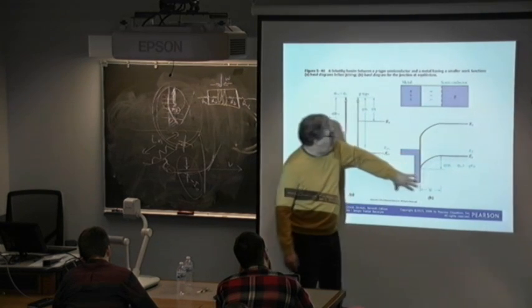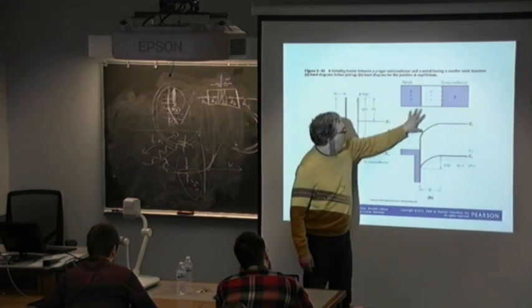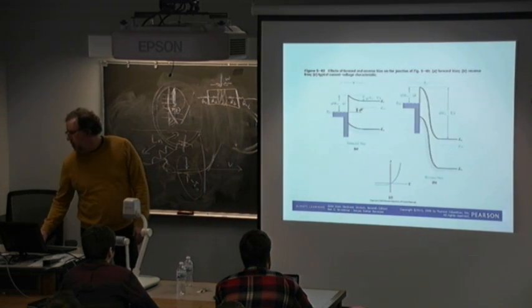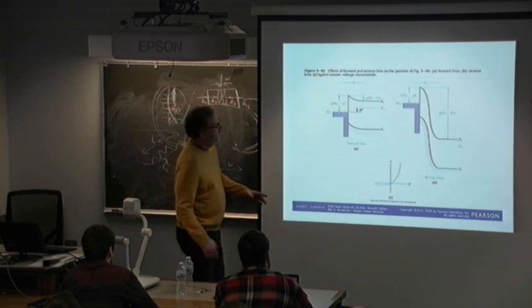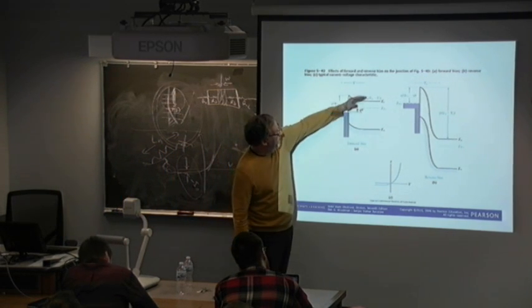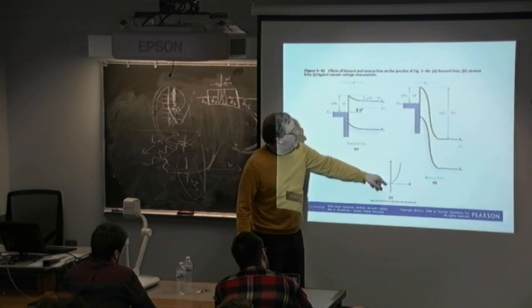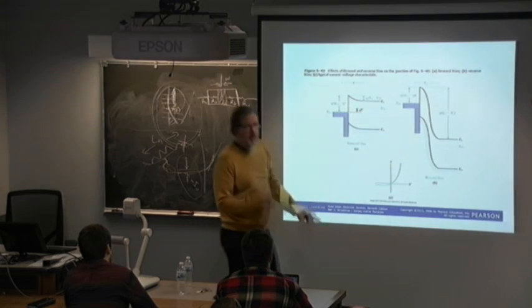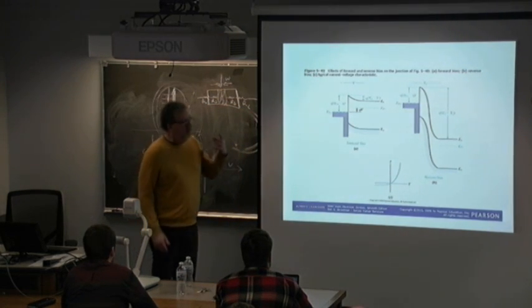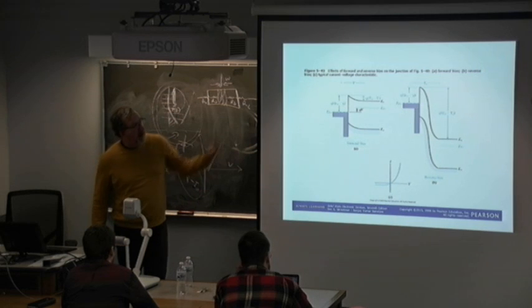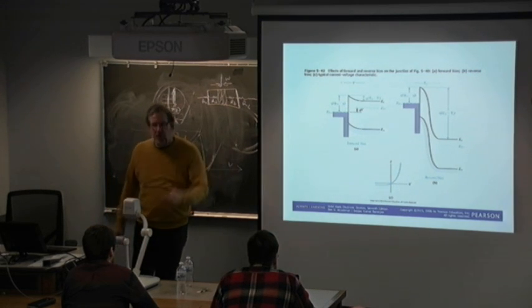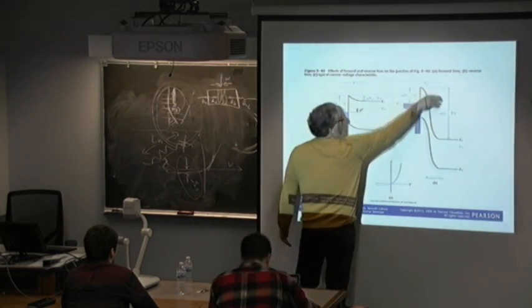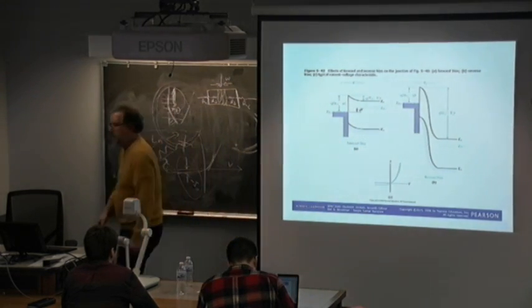So I don't really readily have holes going this way. I don't have electrons going this way. So I have low current, no current. But under forward bias, the barrier lowers. On reverse bias, the barrier increases, and the Schottky barrier height still continues to block or inhibit the backflow of carriers. That's going in the opposite direction, right? Because I want electrons to go from here to here, and the electrons going there is in the opposite direction. That would manifest as a reverse current.